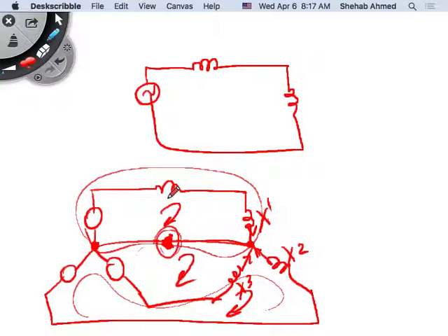So if you want to do Kirchhoff voltage law around the loop, fine, you will have an equation for phase A that includes components or currents and impedances from phase B and C, right? You don't have a choice because of the fact that you have this neutral current. And it's no problem. You can do this for one source and one load, right?